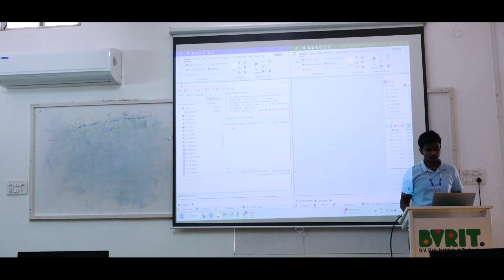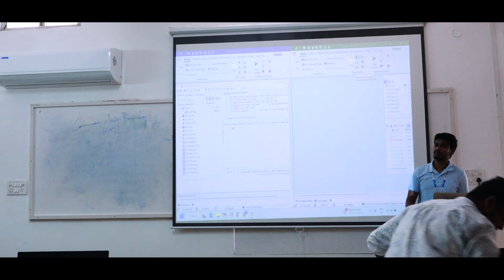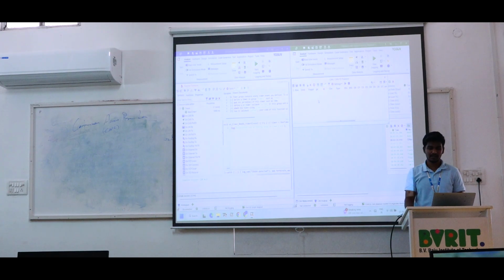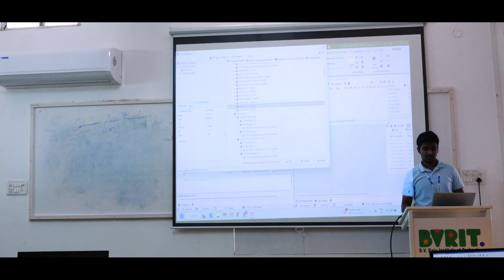Okay. So go to the transmission window in the second tab. Open the CAN transmit. It is showing the transmit window. Right click, new message from DB. You have to add a TCU message, ID number 20. Please add it. TCU message. Click OK.